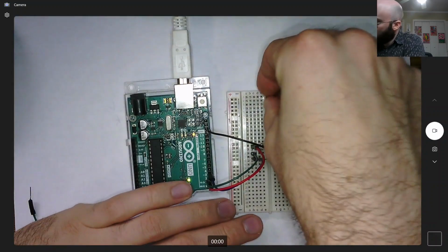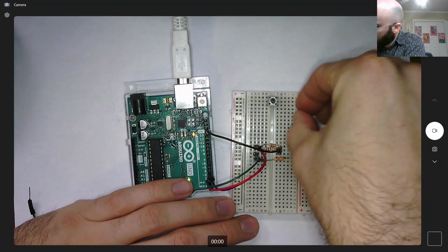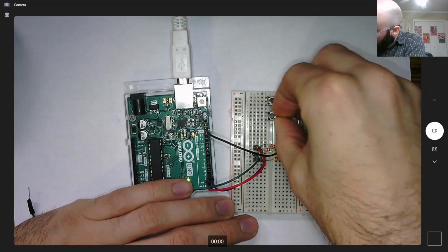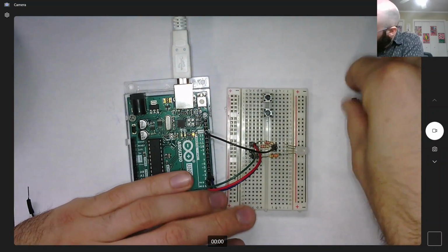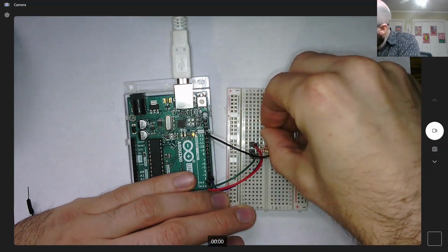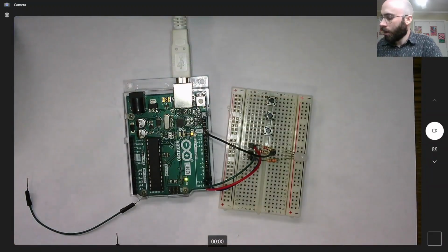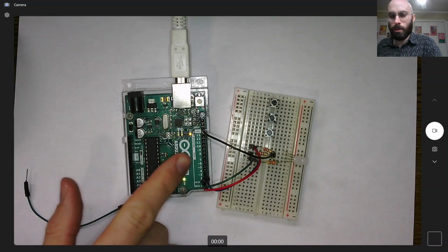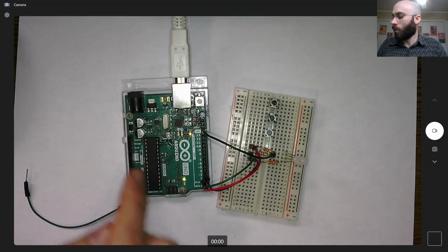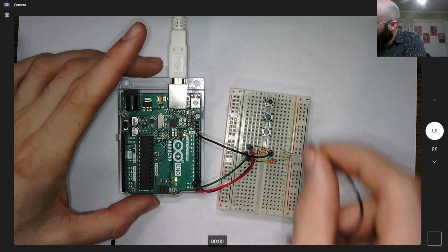So let's start by wiring up the hardware. I'm going to add these 3 push buttons up top here. I should have left myself a little bit more room earlier, but here we are. Alright, so put those there and put those there. And remember, we're going to want to wire these up the same way that we wired up the other ones. We're going to need to wire one end up to ground and the other one up to a digital input, but then enable the input pull up here. So let's wire this all up the correct way.